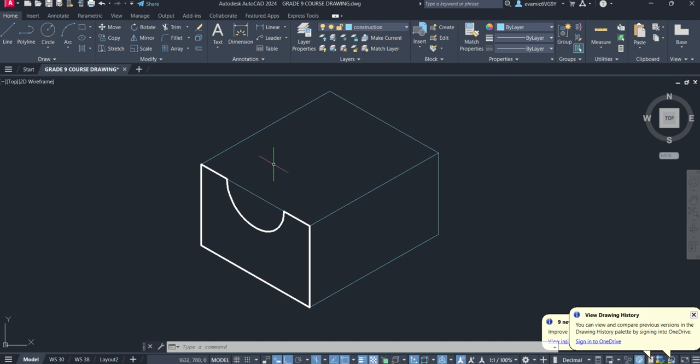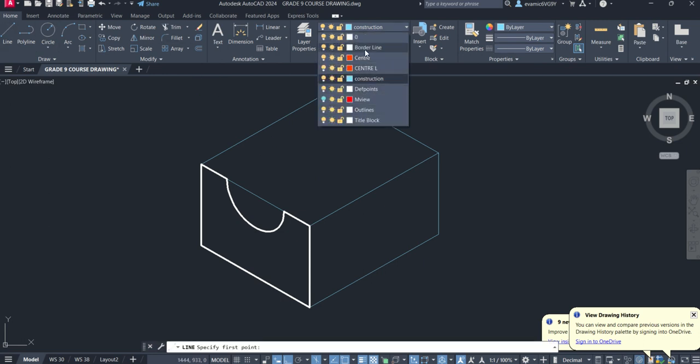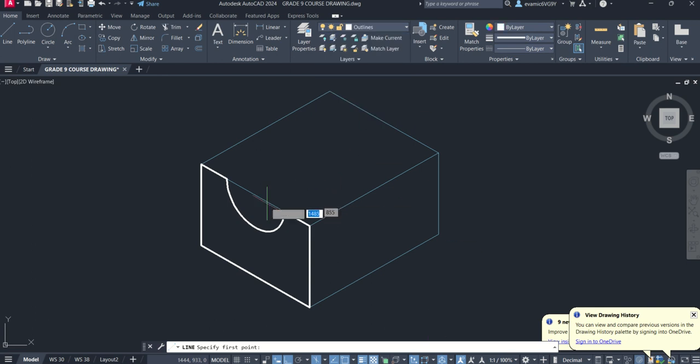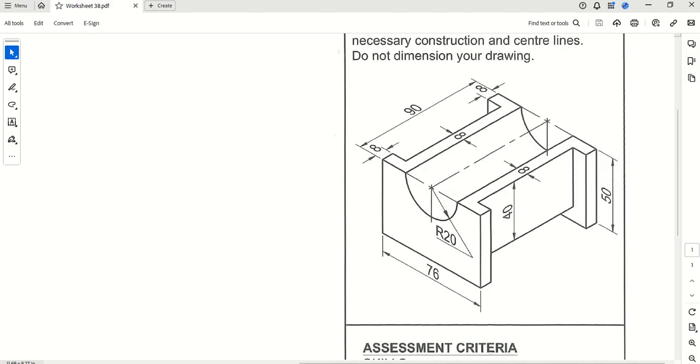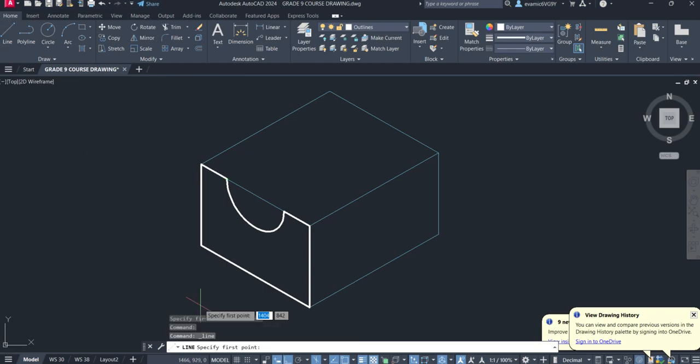start by pushing lines or edges across from the inside of the cylindrical seat, or either edge of the cylindrical seat, all the way to the back. And why am I doing that? Well, if I have a look at my PDF model, you can see that those 2 points have a line that goes all the way through at 30 degrees to the back edge of our construction. So that's a nice place to start.